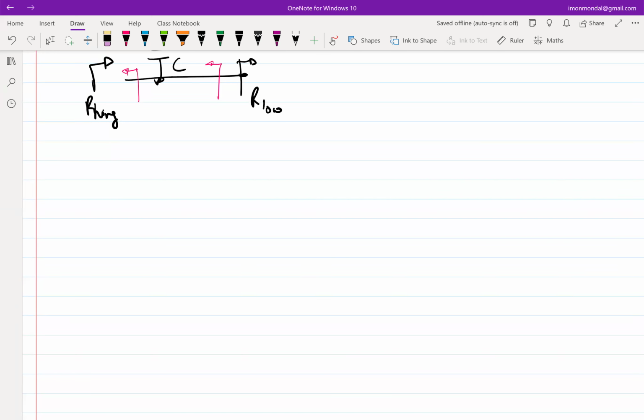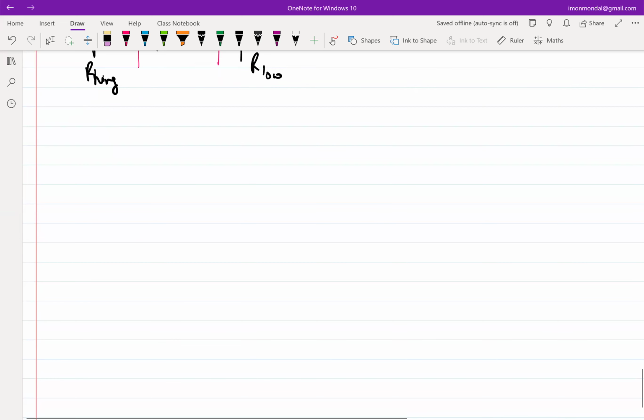But there is a caveat. The caveat is we have completely disregarded the non-idealities associated with a matching network. For example, there is always a resistor associated with an inductor, and a resistor associated with a capacitor, which means there is a loss associated with them. We completely neglected that. So the next part of the lecture is to see what the effect of those losses is and how I can model it. And therein you will see the effect of Q factor coming in. The Q that I have been talking about without really explaining much, that part will come in now.